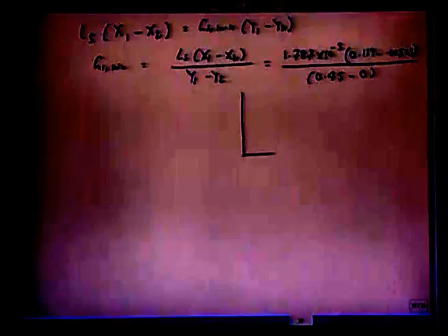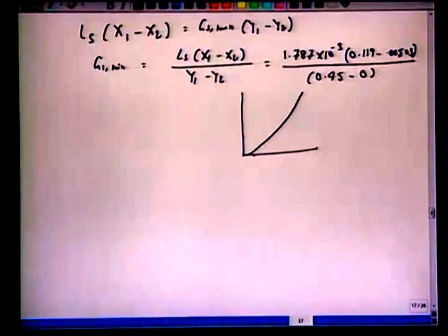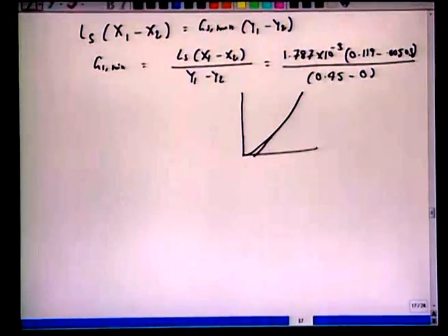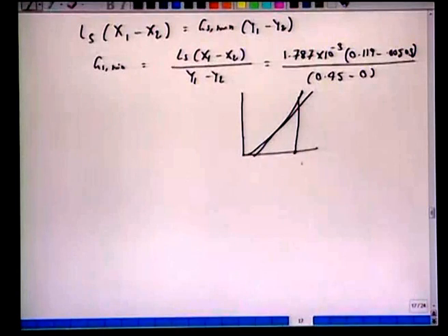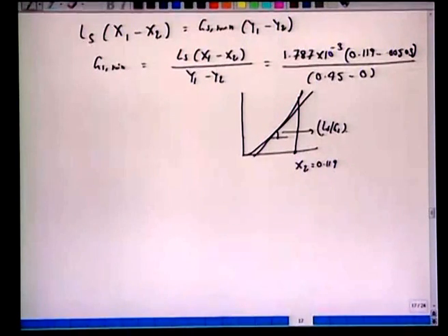That would be your equilibrium curve. From here we have drawn this tangent, okay, and we had this x2 which was given to us. From the slope Ls by Gs corresponding to this minimum amount of Gs, we have this point given as y2. Okay, so this is the y2 which we have got at 0.45.